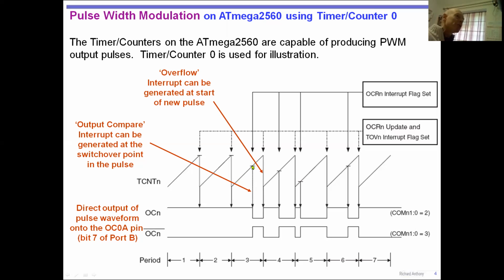Here we don't need the interrupt, we just need to know it's matched that value. So we have 2 points now. We have the point where it starts the count, or where it ends the count, depending on your viewpoint, it's the same place. And the point where we reach this, well, I call it a halfway mark. It's obviously not halfway, but it's in the middle somewhere, right? This middle position that we choose.